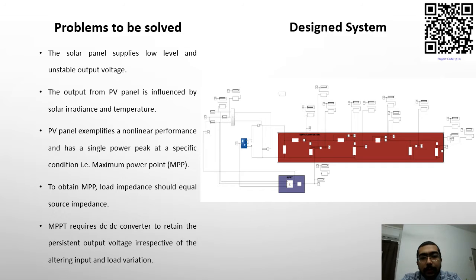The circuit of the DC-DC converter for MPPT application was constructed and designed in MATLAB Simulink software. The input to the DC-DC converter circuit was supplied from a solar panel under various conditions. The PSO MPPT algorithm was employed to test and evaluate the performance of the DC-DC converter. Each parameter of the circuit was designed based on the design methodology and guidelines.